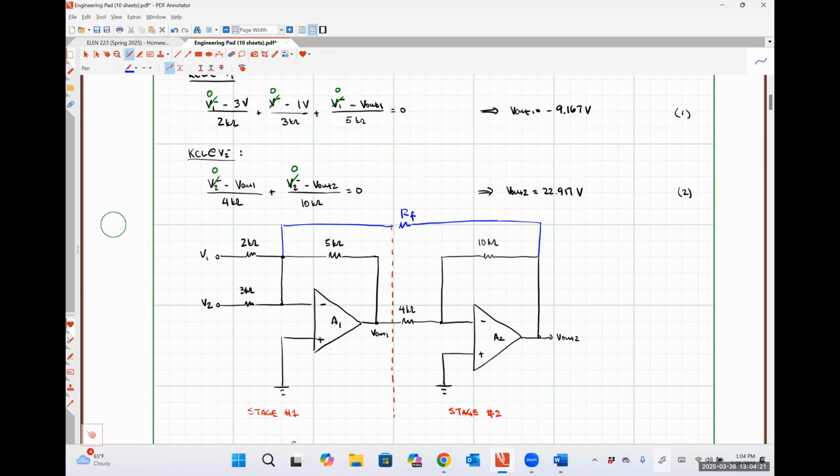So we'll leave that for electronics, but it is a very common practice of using the Miller method to break up feedback between multiple stages so that we can just look at them as: here's stage 1, fed with this Miller impedance; here's stage 2, loaded by this Miller impedance. So that's a problem for another day.